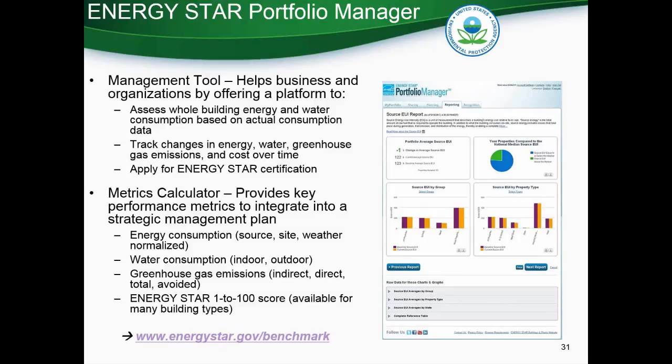Great. And a key resource in the commercial sector is the free online Energy Star Portfolio Manager tool. And I reference this in both the discussion of the commercial program design as well as the benchmarking transparency mandate comments that I made earlier. And at its heart, the Portfolio Manager tool is two things. One is a management tool where businesses, institutions, and organizations can organize their energy and water consumption data, track that over time, and it also provides a mechanism for their most high-performing buildings to apply for Energy Star certification, which is actually available for the top-performing buildings in the commercial sector.